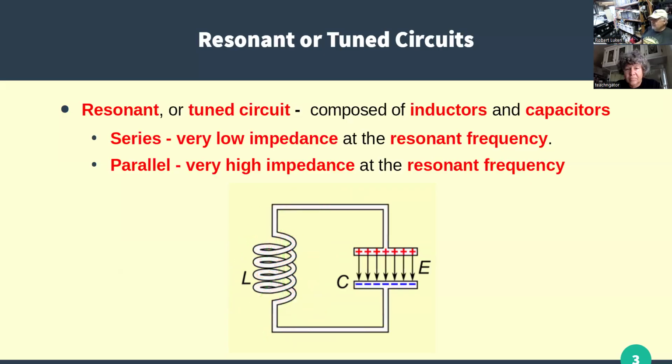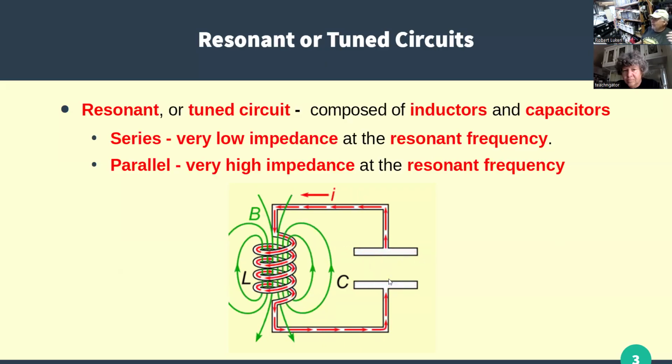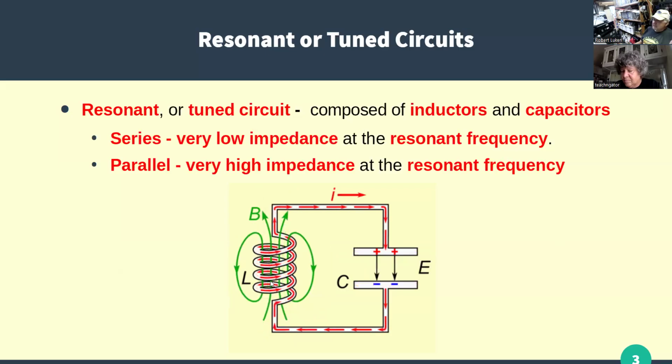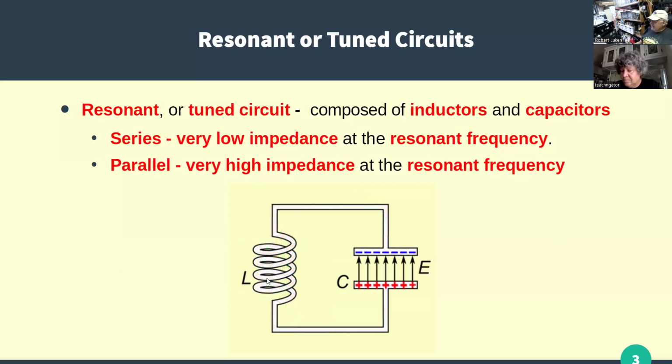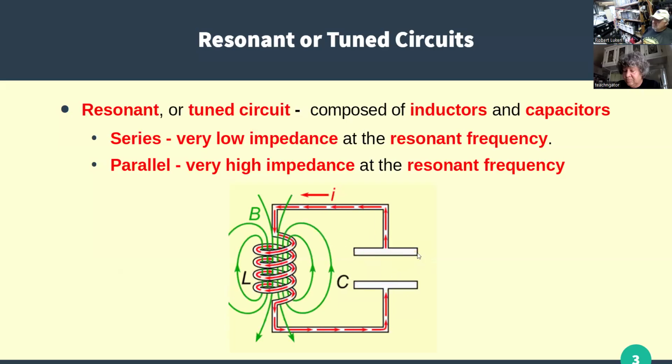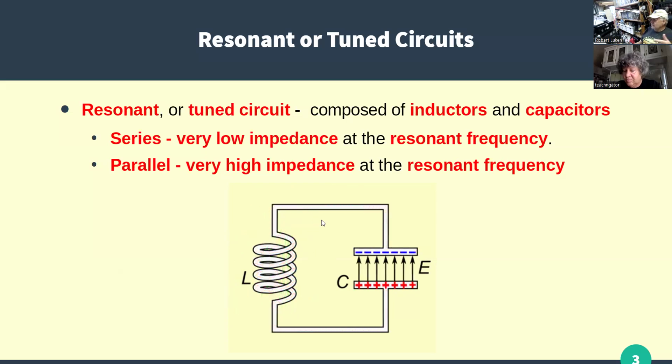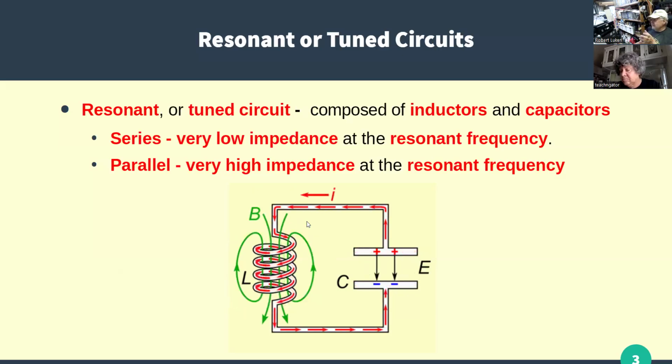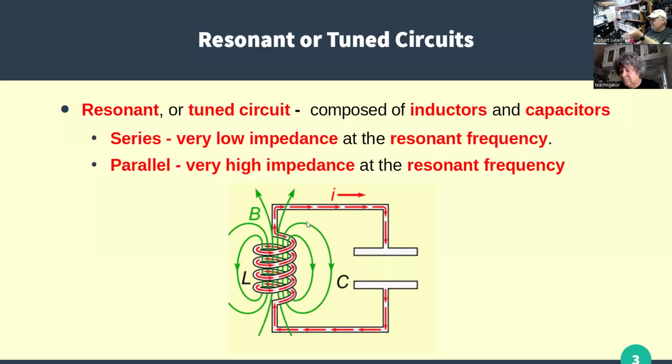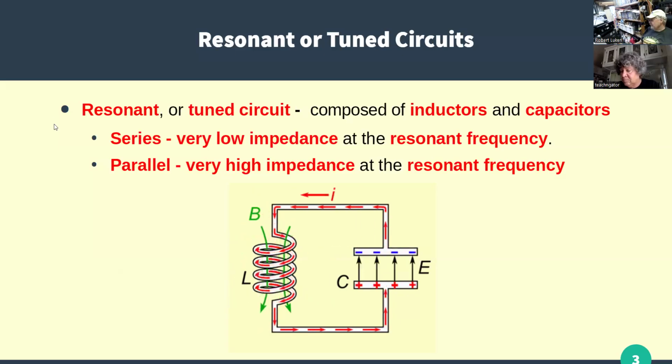So we're converting the energy that is in this electric field in the capacitor over to create an equivalent magnetic field, energy-wise, in the inductor. If there's no loss in the circuit, this would happen indefinitely, and that is what we call resonance. It would just sit there and oscillate, and the frequency of how fast that energy moves back and forth is from that formula I just showed you.